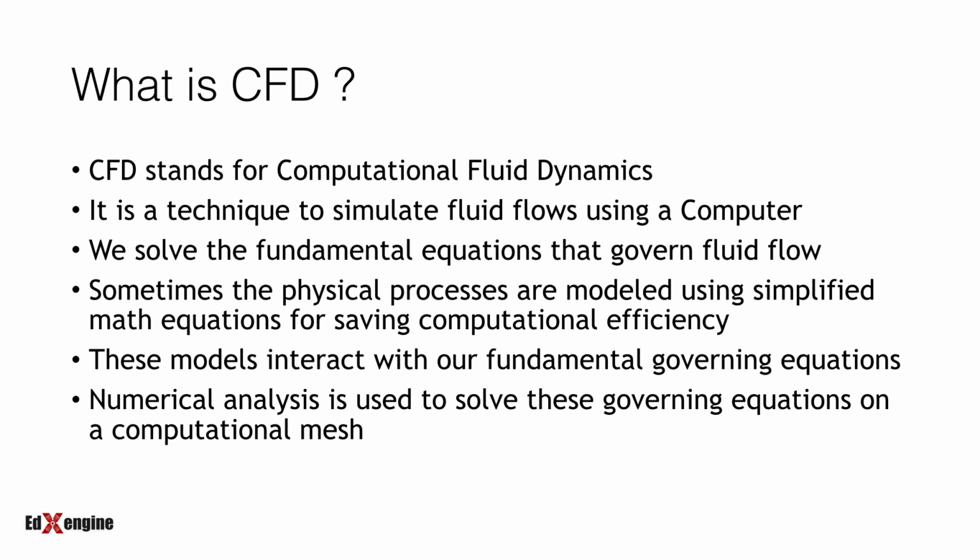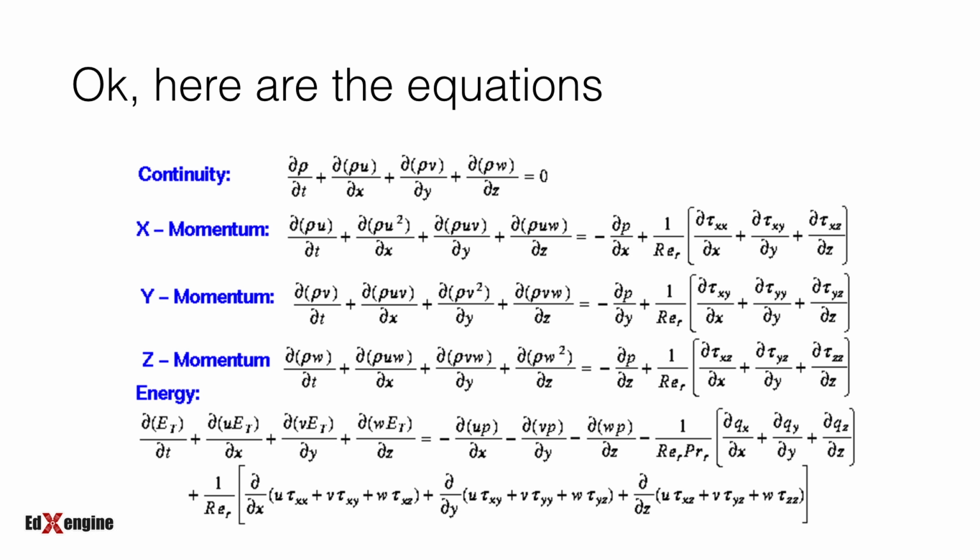The results obtained from a CFD simulation can be used to compute engineering quantities. So let us take a look at the equations. Here you are looking at the continuity, momentum, and energy equations. Continuity equation takes care of mass balance. Momentum equation takes care of momentum balance. The momentum equation is basically the Newton's second law applied to fluid flows. Then we have the energy equation that takes care of energy conservation.